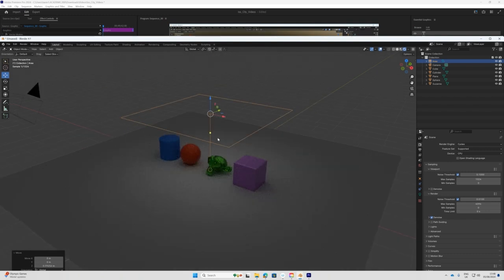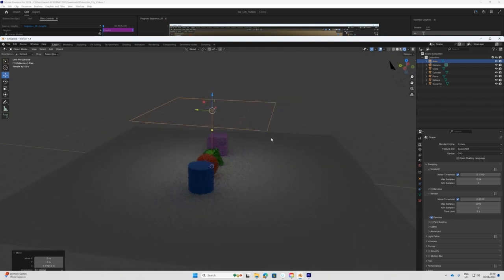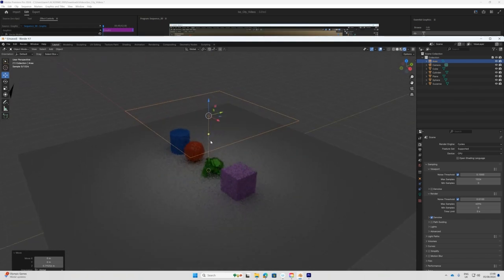See, at the moment it is rendering in real time. That's why, depending on how powerful your computer is, it might be struggling. So one thing I want to do is come here to the render bit, and I go to render. It says maximum samples. The higher the samples, the more calculations the computer has to work. And I suggest you lower this while you're working, and then you can increase slowly and see how long it takes to render, but just keep it low for now.